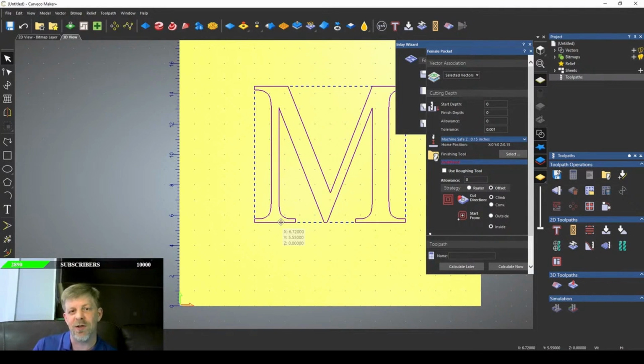The disadvantage of this inlay is we're going to just be using end mills. We're not going to be using a V-carve. The V-carve inlay is a different method. So this is the simplest, most basic method. Typically, when you do an inlay, the bit that you're going to use needs to fit in all of the areas of the vector. Now, sometimes you may have to stretch or make your vectors a little larger. Sometimes you may have issues in certain areas, but you generally want to try to get a bit that's going to fit down into those smallest areas. So the smallest end mill that you can use, the better.